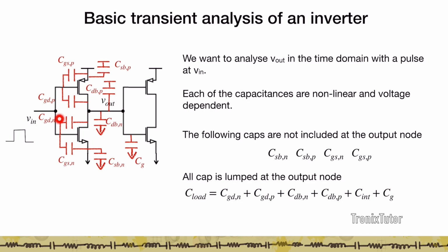In addition to these transistor capacitances, if we are driving a long metal line at this output, then there is an interconnect capacitance that is associated with this node. So if you look at the total node capacitances, it has transistor capacitances of the inverter whose delay we are measuring, the interconnect capacitance of the interconnect connected at the output node, and the input capacitance of the subsequent stage.